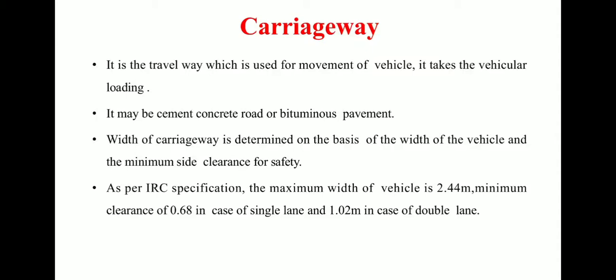Width of carriageway is determined on the basis of width of the vehicle and the minimum side clearance for safety. As per IRC specifications, the maximum width of vehicle is 2.44 meter, minimum clearance of 0.68 meter in case of single lane and 1.02 meter in case of double lane should be provided.